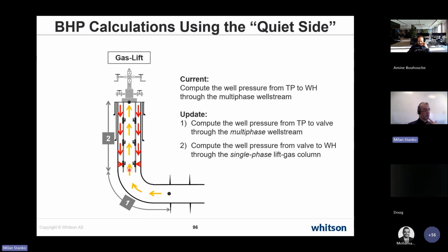Let's say flow through the rest of the tubing using the reservoir rates, and then flow through the production casing using the reservoir rates. And this should be actually similar to the one before. The only thing is that we have a small pressure drop across the valve, because it has to go through a small passage, and then you have some localized losses. So the assumption that the pressures are exactly the same is not 100% correct, but it's a practical engineering assumption.